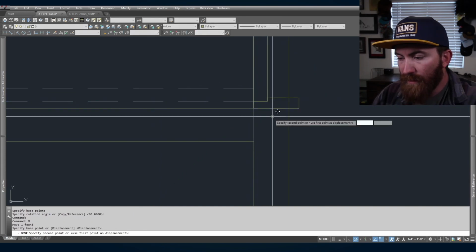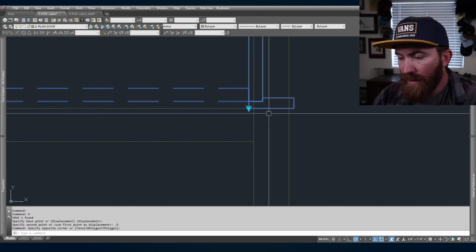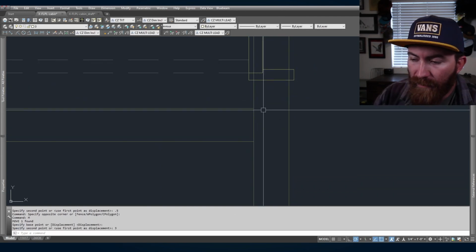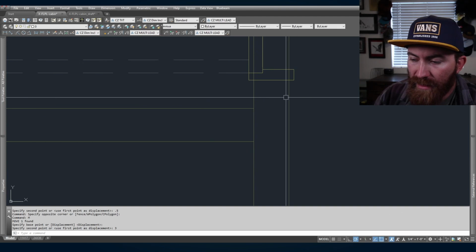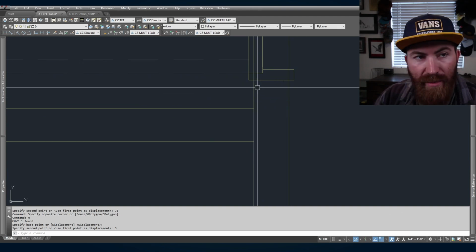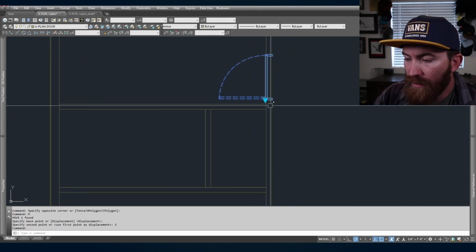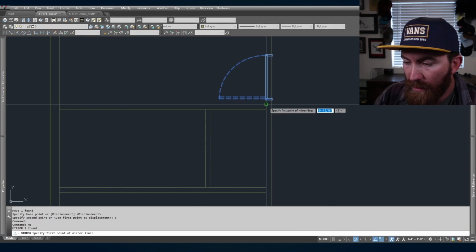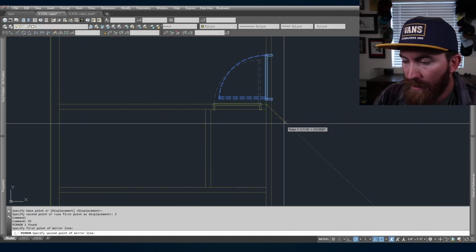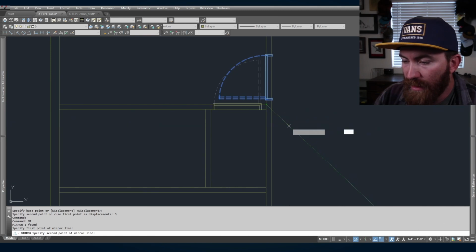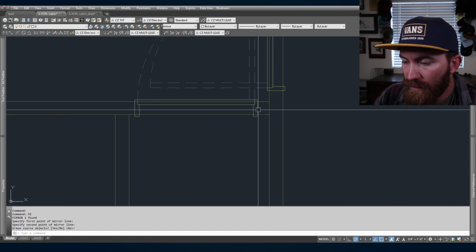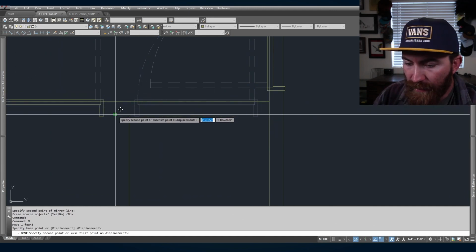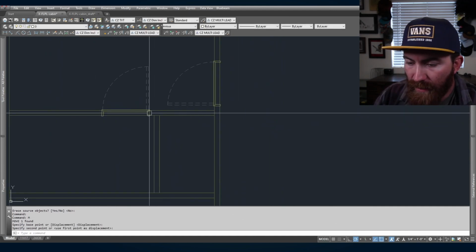So I wanna move it over 0.5 inches, and then I wanna move it up 3 inches. That way when I frame this, I'm gonna have a 1.5 inch stud and a 1.5 inch stud, which is 3 inches. So then I'm also going to hit mirror and select that point in diagonal. Don't want to delete the original. And then boom. So from that wall, got 3 inches.